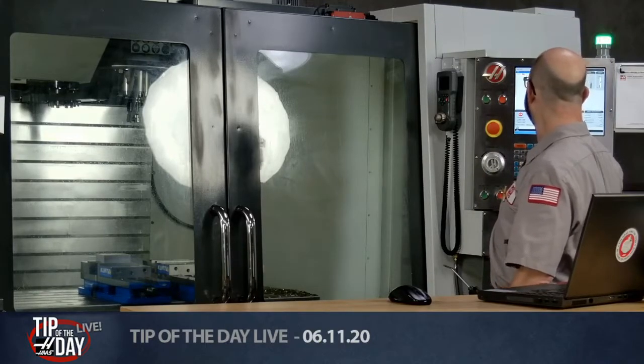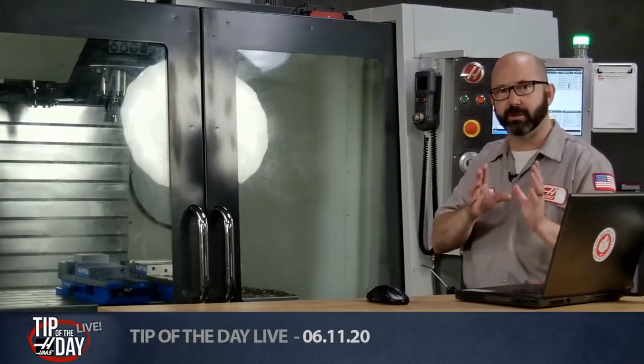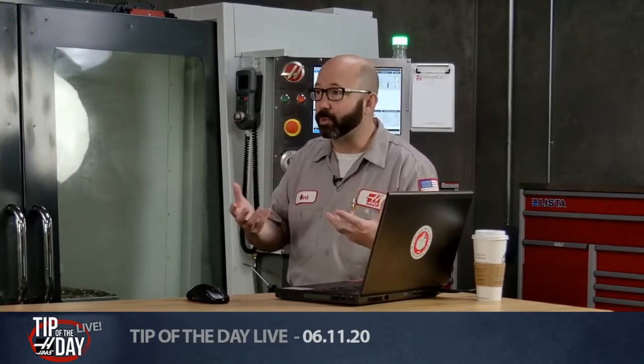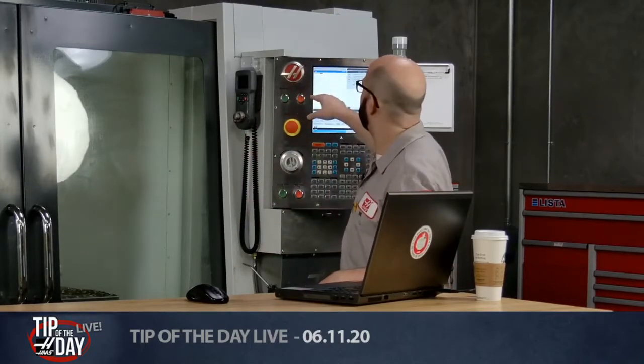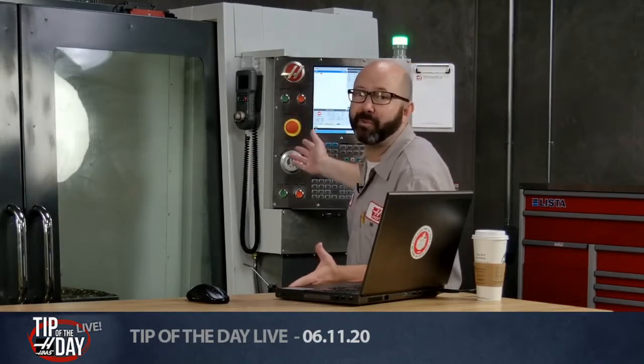If I want to rapid back, I can just add an E value. So G0, X, Y, Z, whatever, and add an E value. The E value, when used with a G0, is going to limit the rapid on that move. So if I go G0, X15, E5,